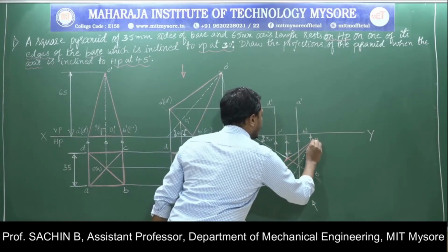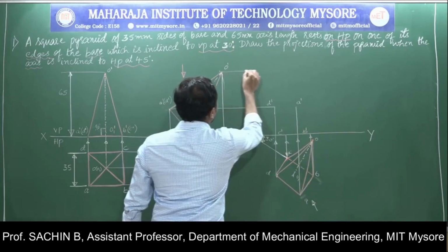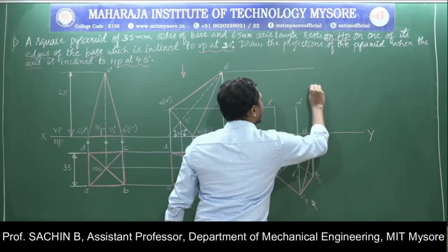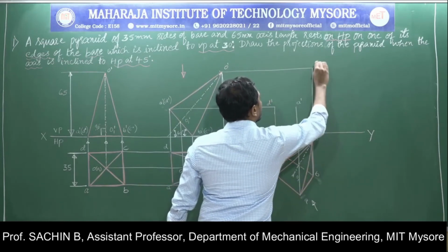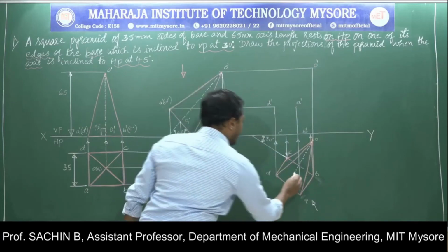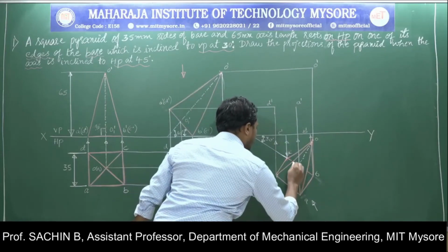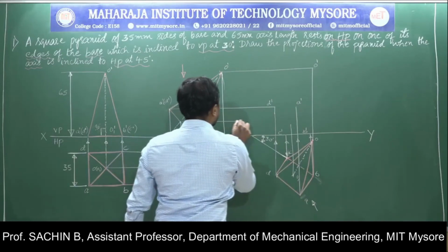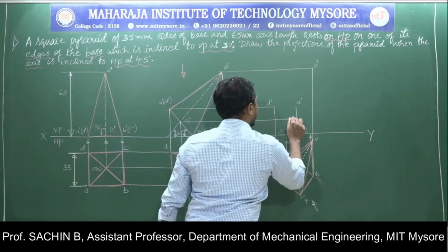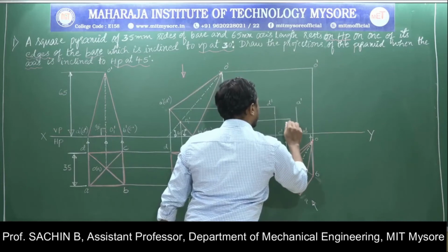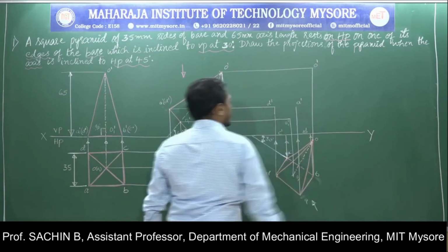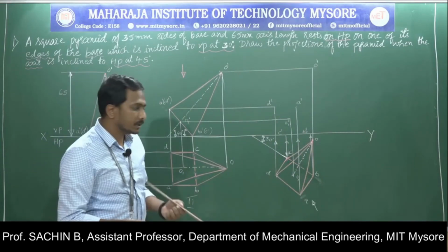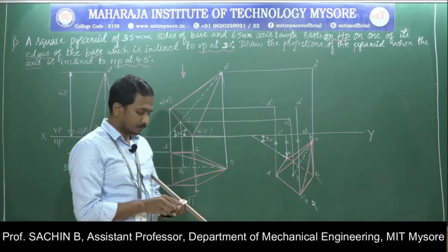to the respective points. Again to get the O point, I am drawing a projection line from this side. Again the same line is drawn to the top. This is my O dash. Again in similar fashion, to get the axis, I am drawing a projection line where that will meet the front view of the object in the second position. Again one more line. This is my axis. Okay, now drawing the projection lines is over.